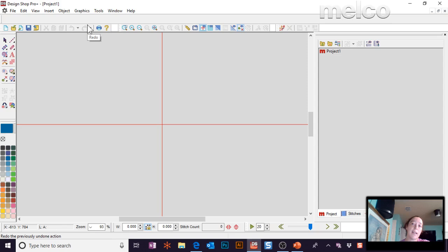Another one was every time I open MOS, the 3 toolbars on the top are stacked. So all the toolbars up here are stacked rather than how they want them. How do I make that come back? Go back to normal. Travis asked that one. So you can do this. Drag your software down, drag it back, snap it to the top, and the toolbars should go back to where they belong. It's a Windows thing. They call that restore. So you're neither maximized nor minimized. And then go back to full screen, and it should restore that way.